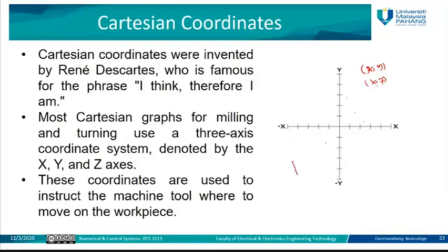We said we have the spindle here, and we have also the workpiece. We need to move this spindle. This spindle will be fixed, and the workpiece is located on the table. The table is moved by using a servo motor. So the table will be moved left, right, for example, front, back, and this will locate the spindle, which goes up or down. Okay. So we need to define this coordinate in order to design our path for the machine to perform its tasks.